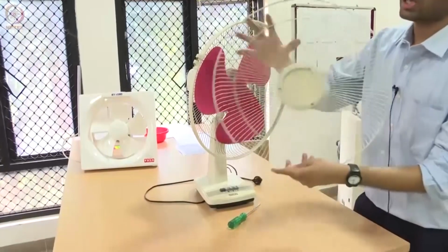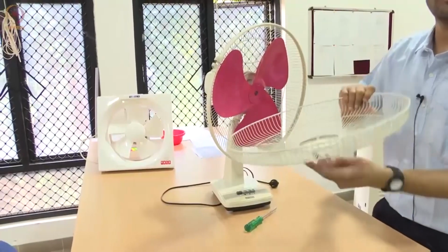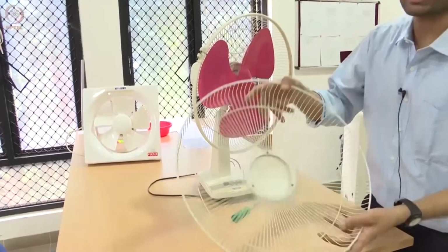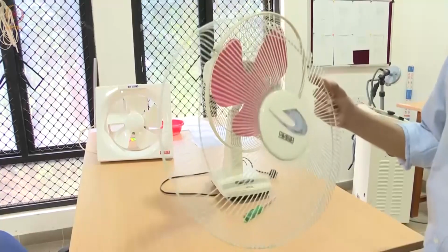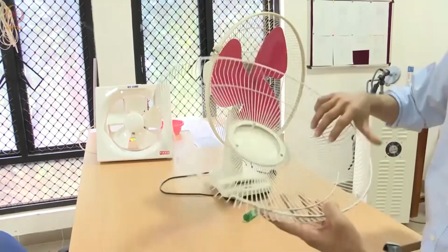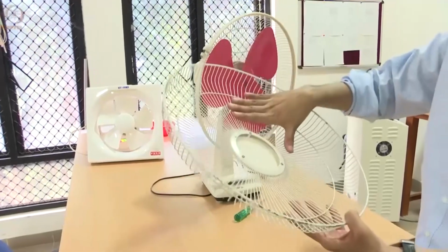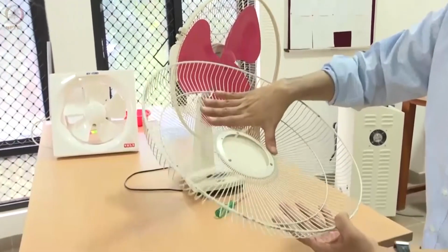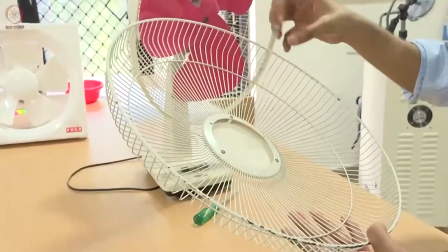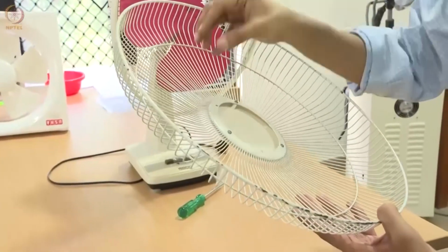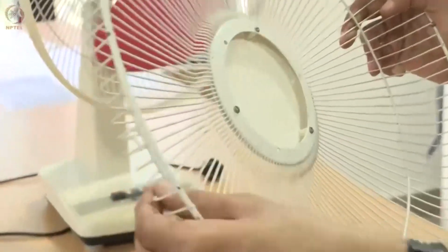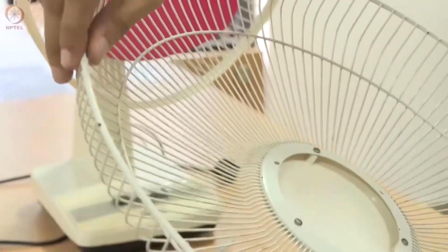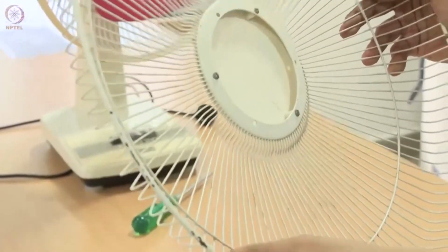You can see it consists of multiple powder coated rods that are resistance welded. So you can see this is mass produced. All this is resistance welded, and then we do a powder coating, a surface treatment. It is just like painting. Please read about powder coating, wherein we electrostatically apply a plastic powder. It clings to the surface, and then it is baked in an oven to create a very durable surface coating that lasts for several years. So powder coating is better than painting.